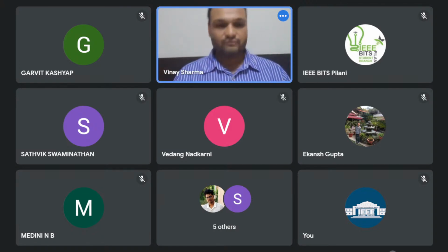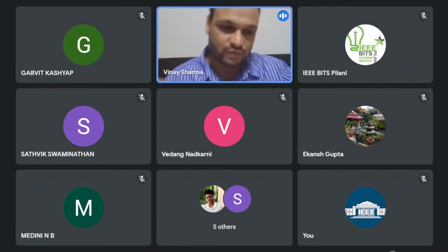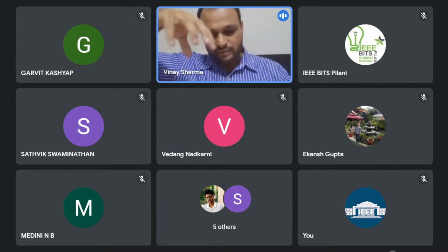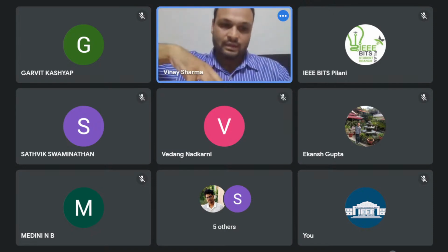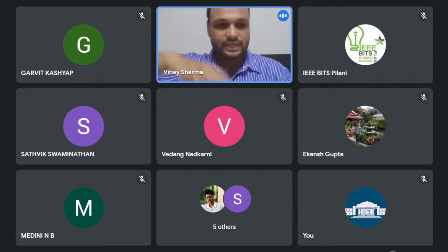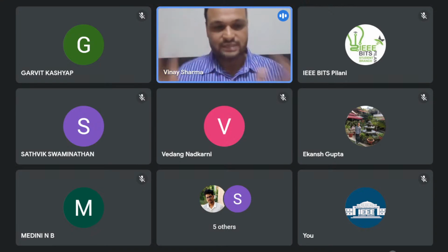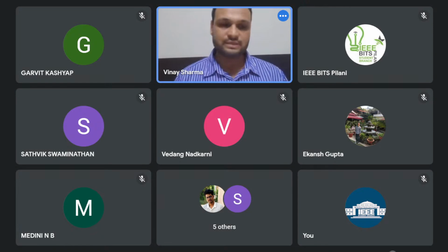Another thing is, when we print the structures one on another, there is a technique called photolithography. Your pattern should lie exactly on top of the previous one. Since the size is becoming smaller and smaller, there are various issues like defocus issues and spot issues. So this is also one of the challenges, that our focus spot should be as small as possible in the nano dimensions.